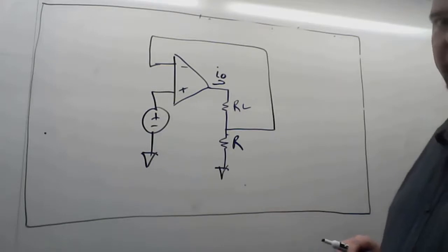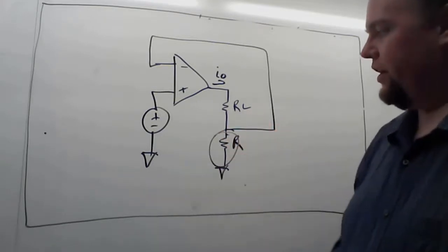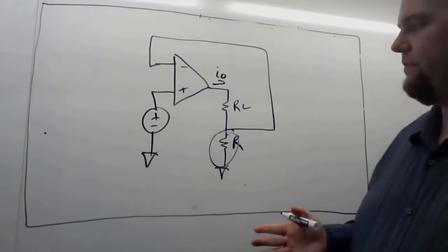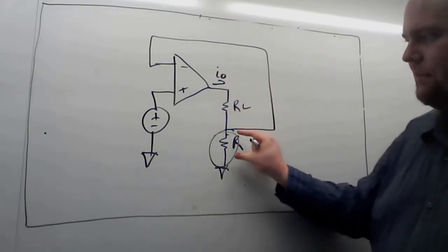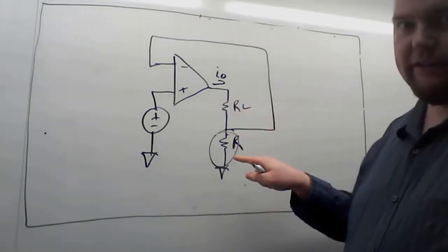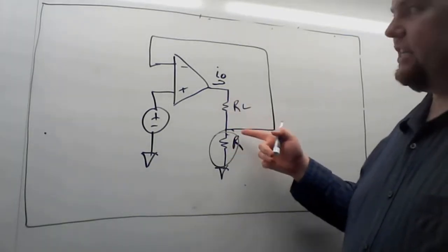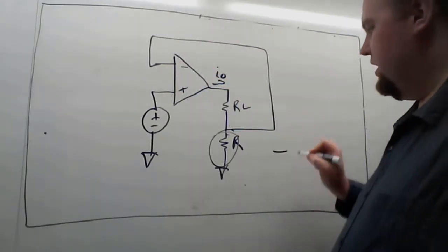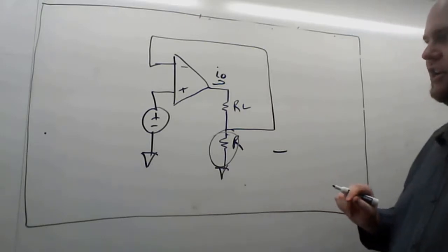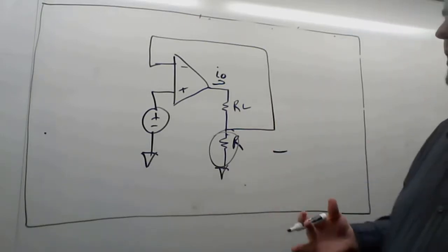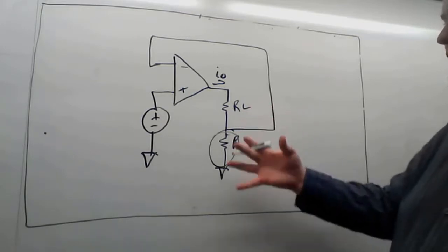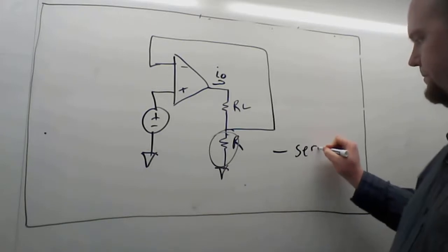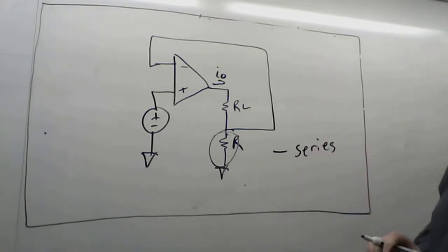So currents, we always sample in series. Again, we are sampling this current in series. The way we are determining how much current we have flowing out of this op-amp in this case is by putting a resistor in series with that output current, sampling that, and using that current signal to drive the circuit. Because our output is we are measuring a current, it is the change in the output current through the load resistor that changes the signal we get. So the output is a series.